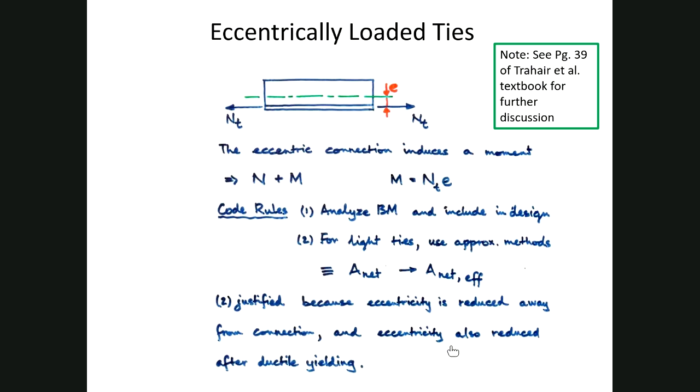What we have done up to now was a symmetrically loaded section. We load it straight through the centroid of the section, or very close to the centroid of the section. The centroid of the section would be halfway through the thickness of the section. We connected onto both ends and loaded it, so it's very, very close to the centroid of the section.